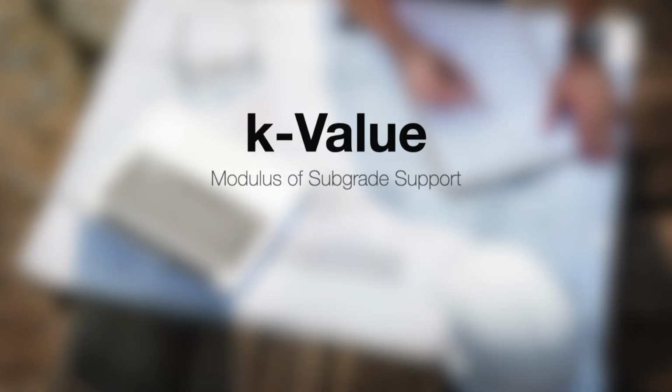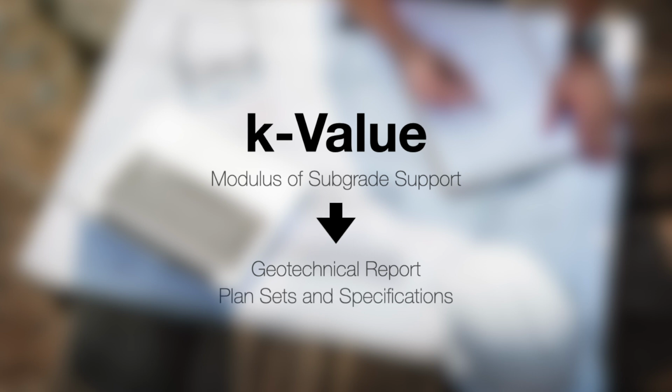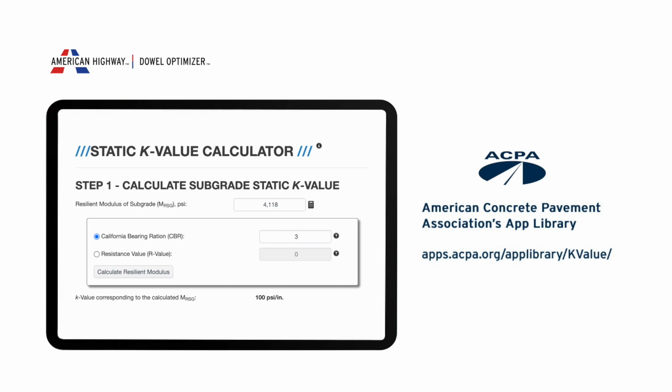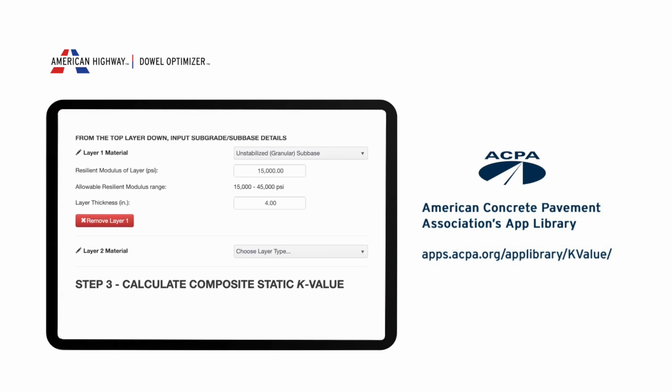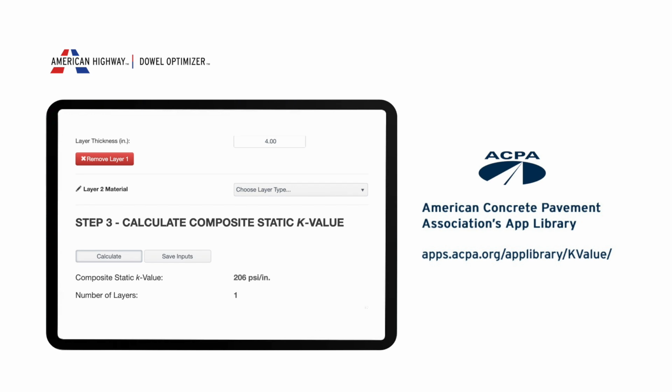The K-value, or modulus of subgrade support, is often found in the project's geotechnical report. However, it's not uncommon to see it referenced again in other parts of the plan set or specs. If no K-value is provided, you can estimate one using a free web app developed by the American Concrete Pavement Association.